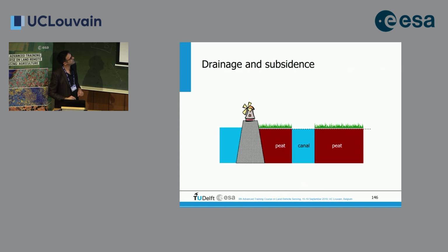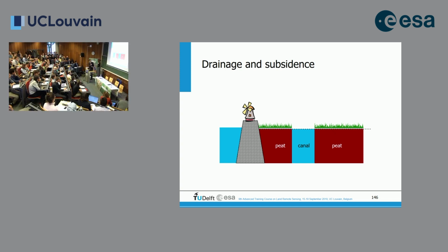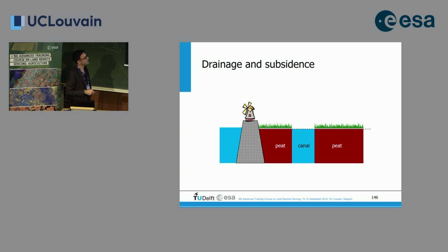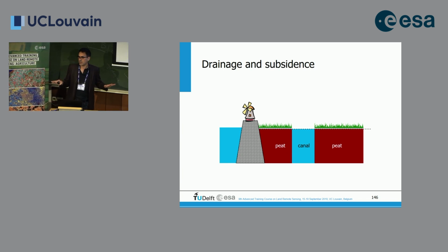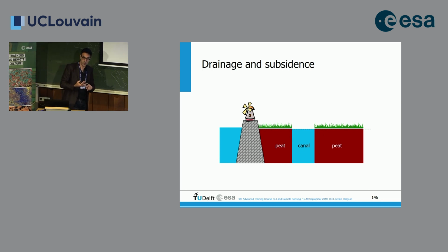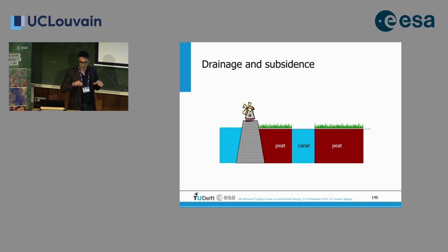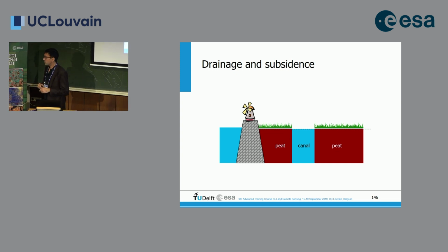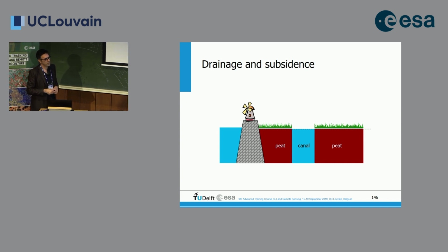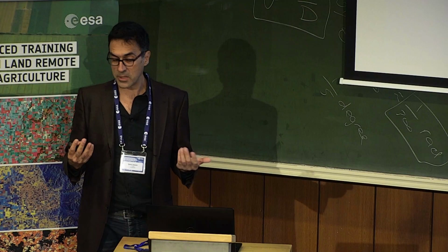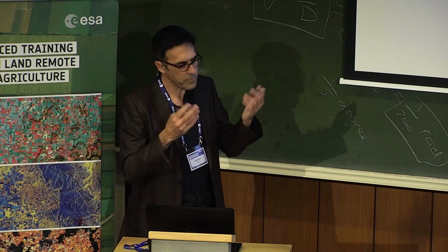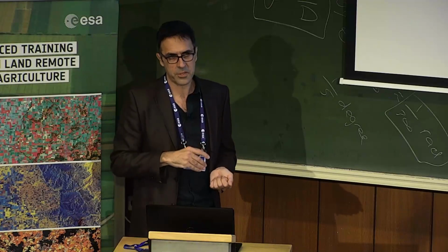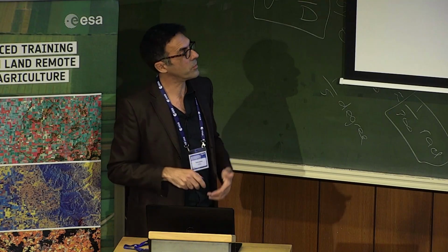Now the problem is this: we have land which is already in large parts below the sea level. So we have the sea over here, and we have these famous dikes. Right, the dikes protect the country, and behind the dikes are these pastures, the grassy fields where the cows are going, and because it's a delta area, here we're at the confluence of the Rhine River, the Meuse River, and the Schelde River. There's a lot of organic deposits of the rivers. And peat is one of the most important of them. Peat is a type of material which consists of organic material, so rotten plants and rotten animals, and it's kind of deposited on top of each other. It's very fertile, so this is why it's a good soil for the grass.